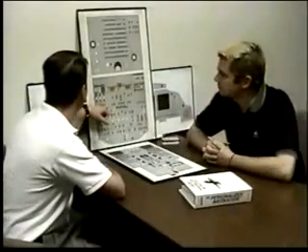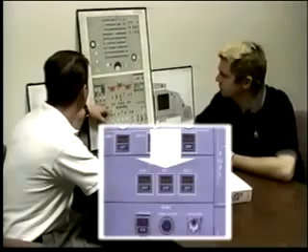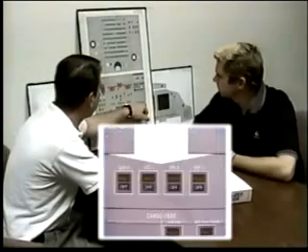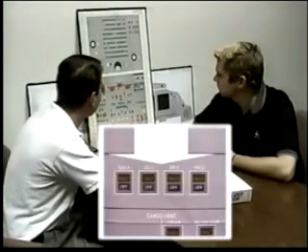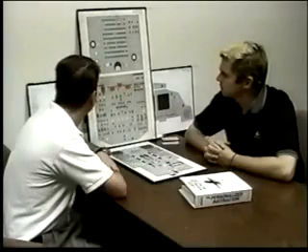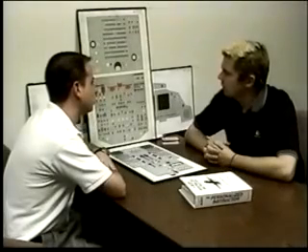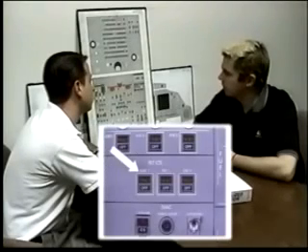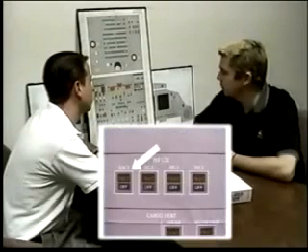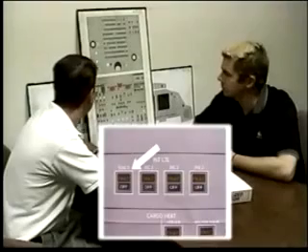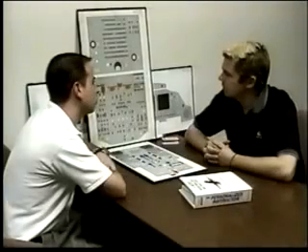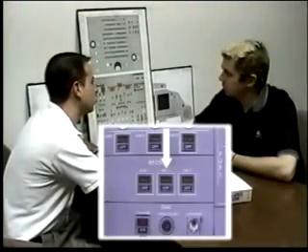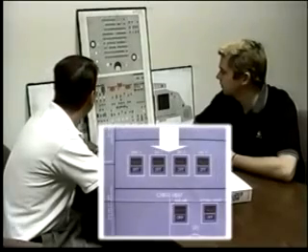Flight controls. Above the captain we have ELAC 1, SEC 1, FAC 1. Above the first officer we have ELAC 2, SEC 2, SEC 3, and FAC 2. What do the ELACs control? ELACs control the elevators and ailerons. ELAC 1 primarily controls the ailerons. ELAC 2 primarily controls the elevators. SECs. The SECs control the spoilers and the elevator.